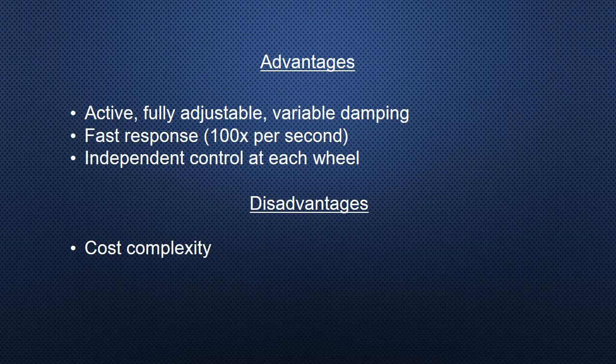They have fast response, as in it is a simple circuit in which by varying the voltage we can change the flux, which in turn changes the magnitude of the damping. And they have independent control at each wheel, meaning that they can vary independently at both the wheels according to the situation. And the only disadvantage they have is that the process of making them is very complex, and hence it is costly.